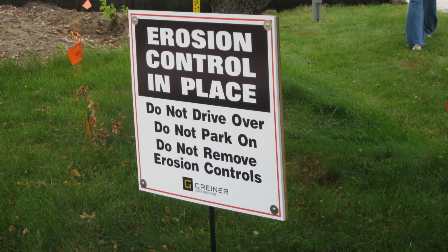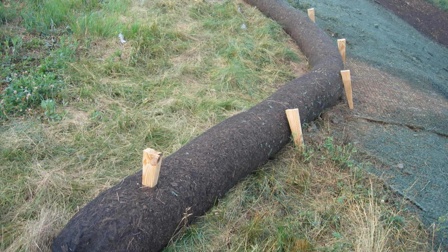During roadwork and ditch maintenance, remove as little vegetation as possible. If soil is left exposed within 200 feet of a water body, you must install temporary or permanent erosion protection within 24 hours. Planting native vegetation with deep roots is an easy and economical way to reduce erosion by up to 90%. Additional structural controls can be implemented to further prevent erosion.